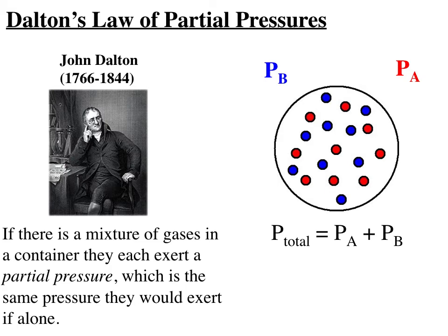So now when I'm mixing A with B, there's no interaction between the addition of the extra molecules in the chamber compared to what interaction there was prior to the introduction of the second gas. So both of these gases mixed together are still behaving ideally. They don't have any interaction with one another, so they won't affect the pressure of one another. So whatever pressure they would have exerted individually in the chamber, they will just now compound to exert as a sum of their individuals to give some higher total pressure when you mix them together.